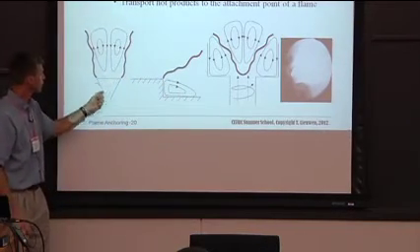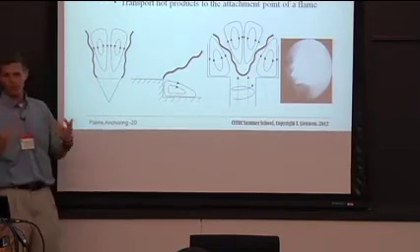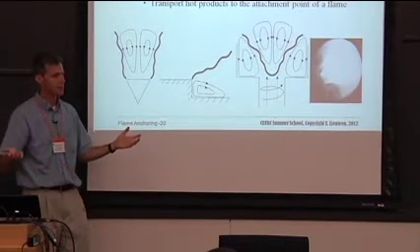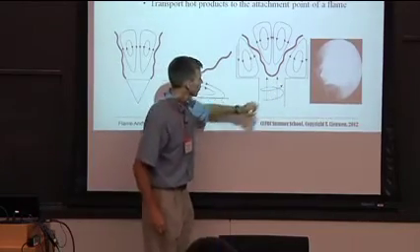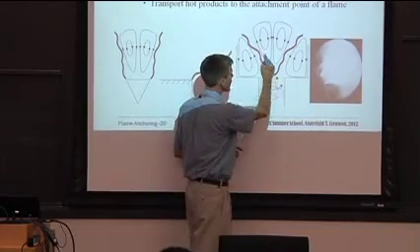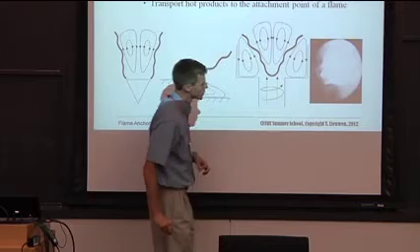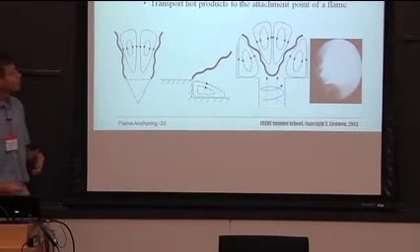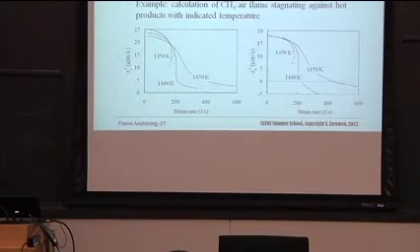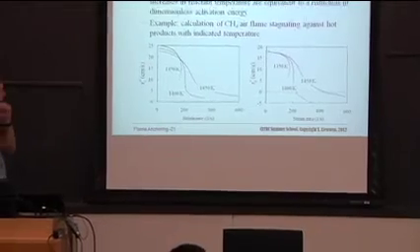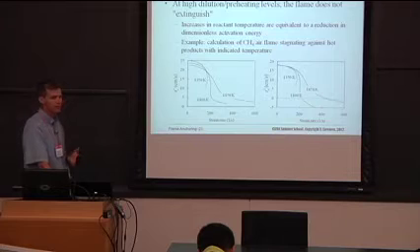Same thing happens here. Here's a bluff body flame, like would be used in an afterburner. Similar deal. You force flow separation, and by flow separation, you have stagnation pressure loss. You say, I've got to stabilize my flame, so I'm going to lose a little stagnation pressure. Or this is a swirl flame, and here I have this vortex breakdown bubble, which causes some flow recirculation, and actually this rapid expansion gives me flow recirculation. So oftentimes this is what's used to stabilize the flame. And this is interesting because when you start piloting flames, or when you have very high preheat, this whole phenomenon of flame extinction kind of goes away.